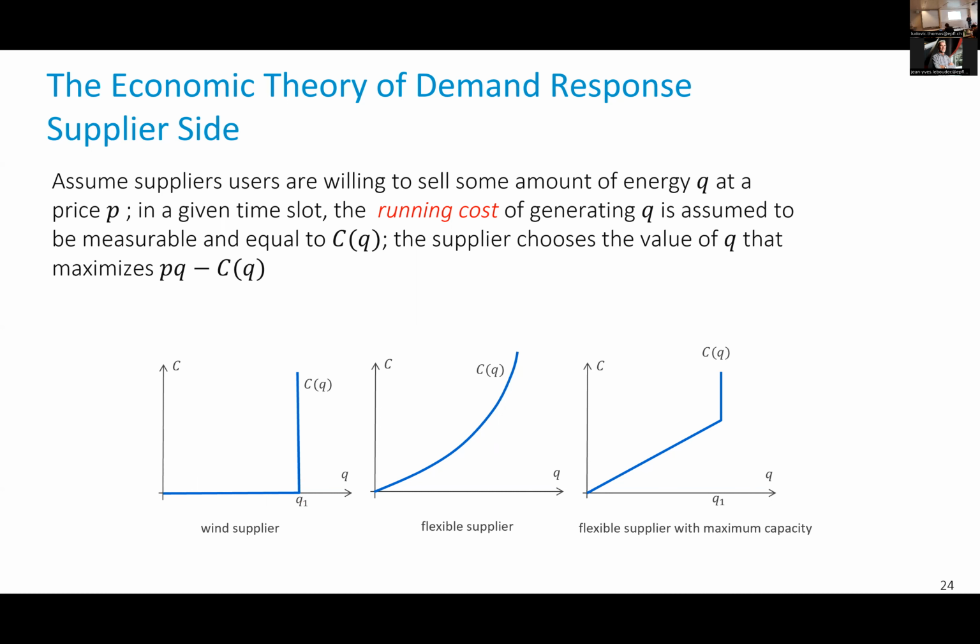It comes at no direct cost, because there's a cost, which is the money I don't receive for the electricity that I've thrown away instead of injecting it. But in terms of generation costs, there is 0 cost, and an infinite cost of going above. So Q1 is what it can produce, given the insolation or the wind speed and the orientation. And so that's different supply curves here.